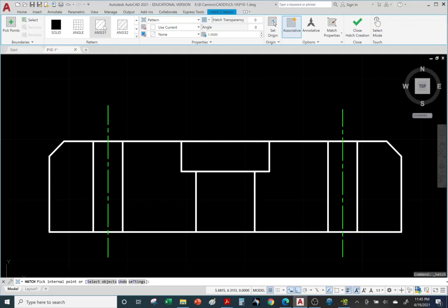It's very simple. Okay, so you try and use one pattern per part. Later on, when we do assemblies, at the end of the last two chapters, you want to use a pattern for each type of part. We'll cover that again in a later chapter. Okay, so I'll go with the very simple ANSI 31. ANSI, American National Standards Institute, came up with these patterns, at least for these first two, right? So let's go to ANSI 31.